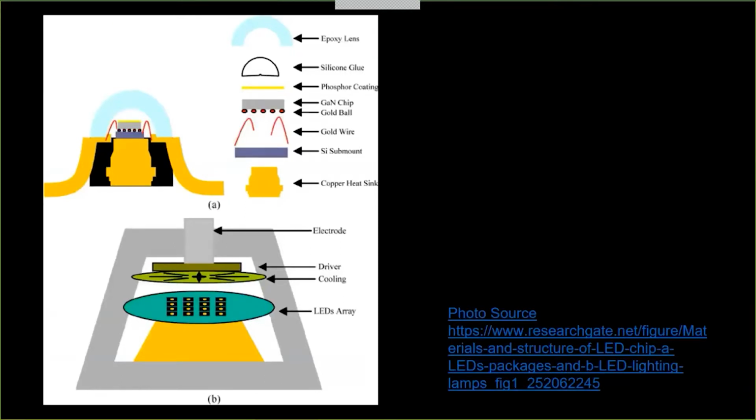Now a little bit about what an LED looks like. If you're not familiar with them, they generally look like a little piece of plastic with some yellow silicone or something. Looks like a phosphor coating on the top, but there's a copper heat sink underneath that. And I'm telling you this because when I set it up, I used copper as my default material for these LEDs. Even though it doesn't look like copper, there's a big heat sink in there which is helping to draw the heat away from the actual diode and hopefully transfer it into the circuit board.